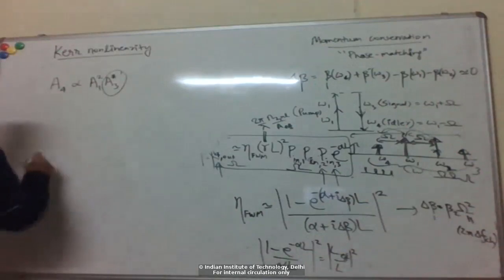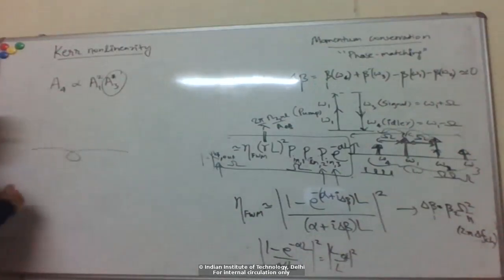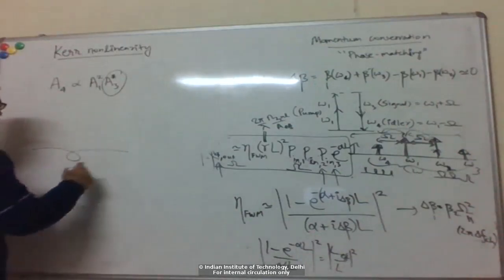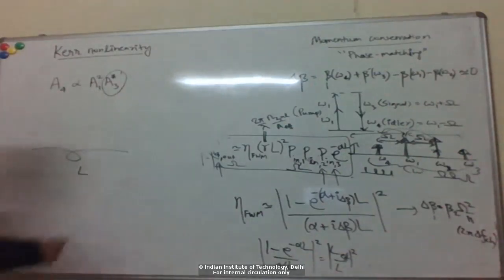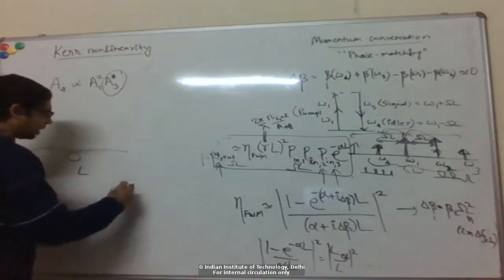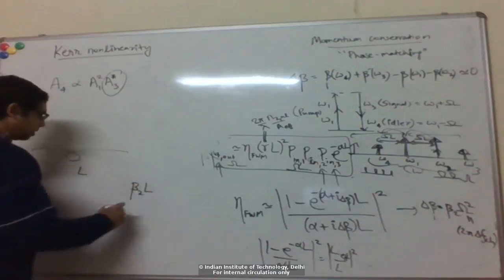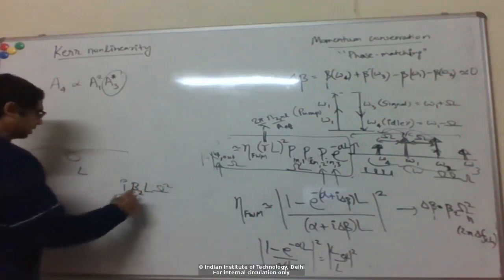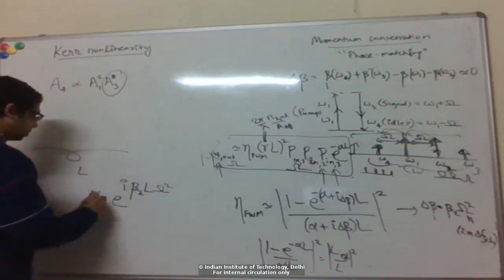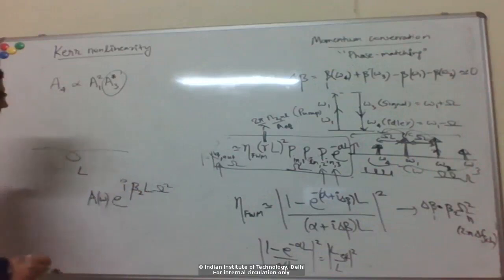For example, let's say you have a link, and you get some dispersive broadening. Typically we saw that the broadening depended on this GVD value times the length. So we acquired some phase like this, and the spectrum was multiplied by some phase like this, which was giving me the broadening.